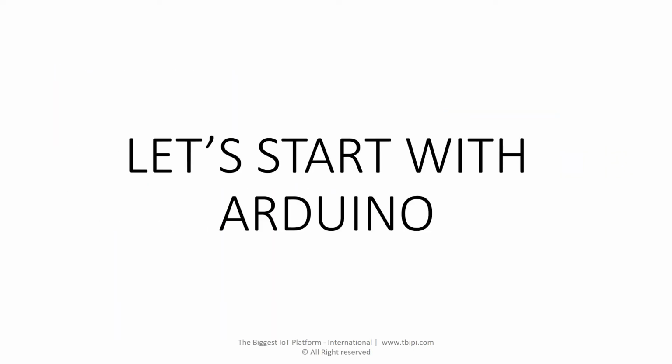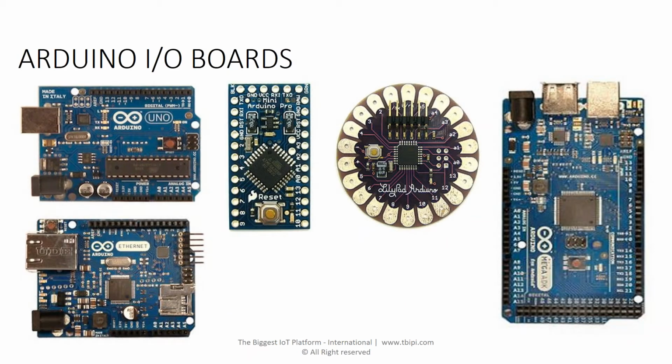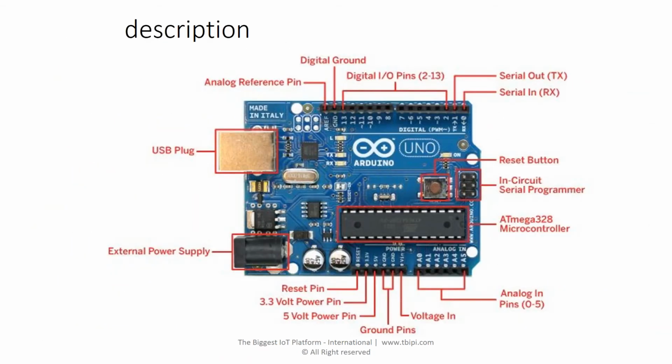So microcontrollers, as we started, are like a programmable system on chip, and Arduinos. The basics of Arduino require this Arduino Uno board, on which you have the ATmega328 microcontroller along with the digital input output pins and analog input output pins. So 0 to 13 are digital input, digital output. A0 to A5 are analog input pins. And then you have a USB plug to connect this to a PC and program it.